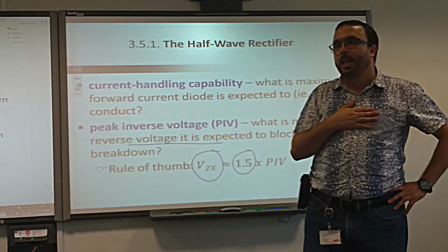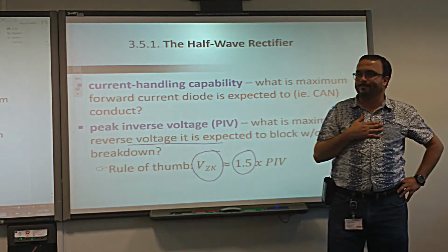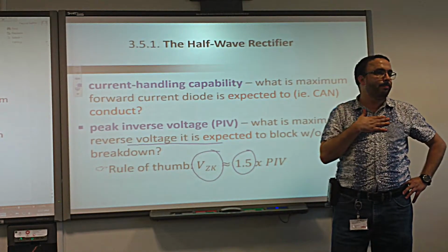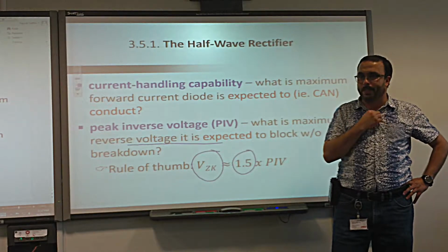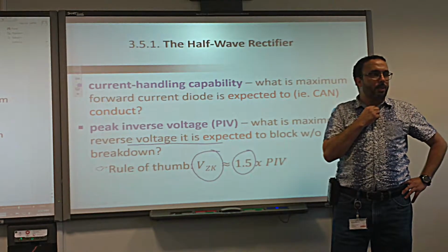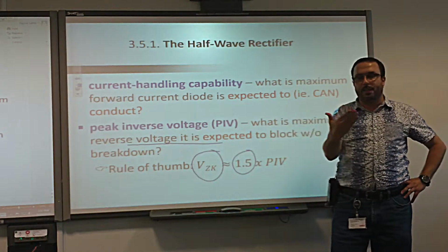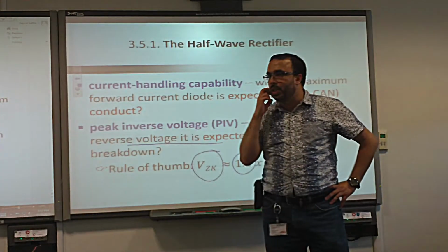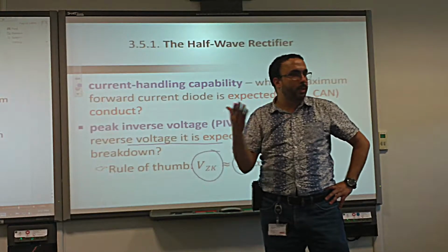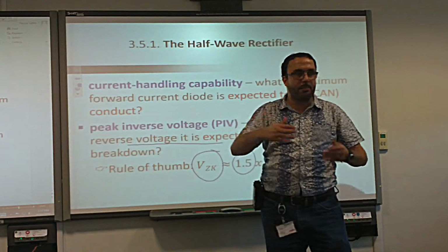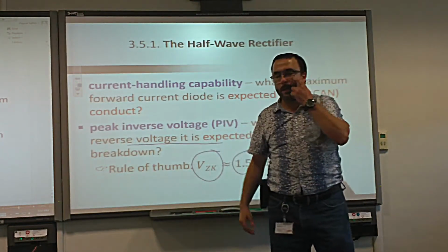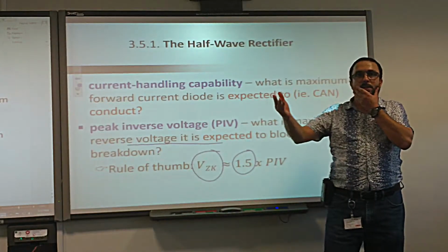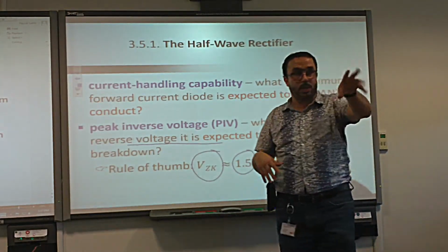Meaning, let's say I want to build this rectifier in the lab. I want to sell it, make business, make money. So I take this simple circuit and I find that the PIV, the peak inverse voltage or the peak reverse voltage of this diode, is Vs. That's the maximum reverse voltage we can have here. How much is it? Let's say Vs in this case is 6 volts.